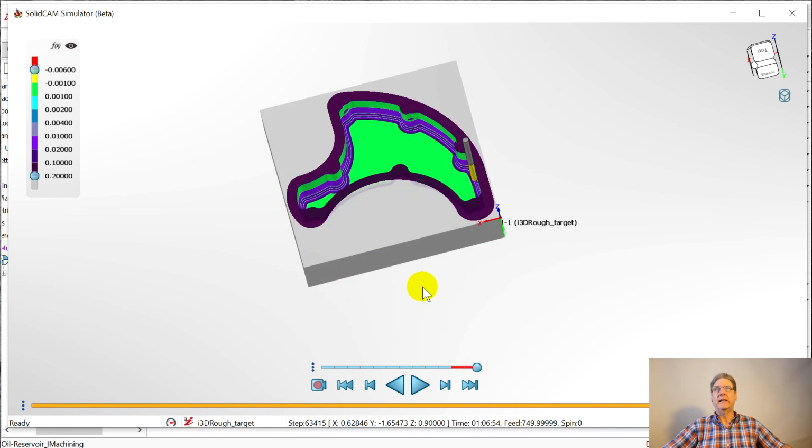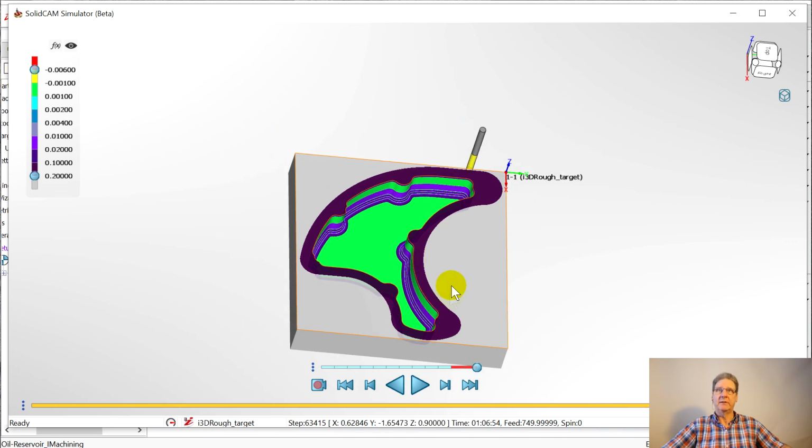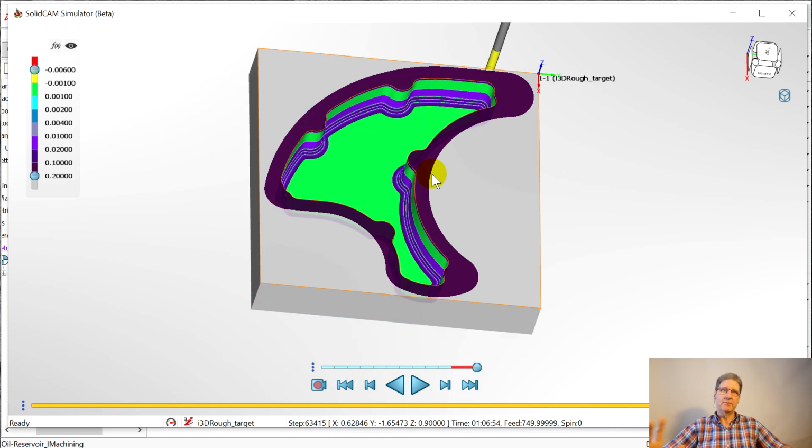So these are the kind of episodes I'm having with iMachining, 3D iMachining, all the iMachining. You know, I'd rather have it a simpler kind of thing like Visual Mill. You click with Visual Mill, you just click and say, okay, I think it's HSS. And then it kind of starts and does circles and works out, and you control how deep the cut is. You control the step overs. iMachining's got a big algorithm and it's doing fancy stuff, but I just as soon have a little more control of these adaptive toolpaths, at least to get it so that it's cutting the sidewalls right.